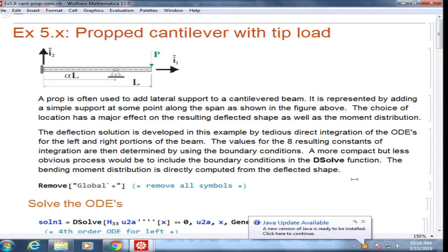We do not need to find moments. We are just writing everything in terms of displacements to solve it. So we will write our governing differential equations in terms of displacement, and we will write our boundary conditions in terms of displacement, so that we have one variable to solve for. Okay, everybody on the same page? Perfect.